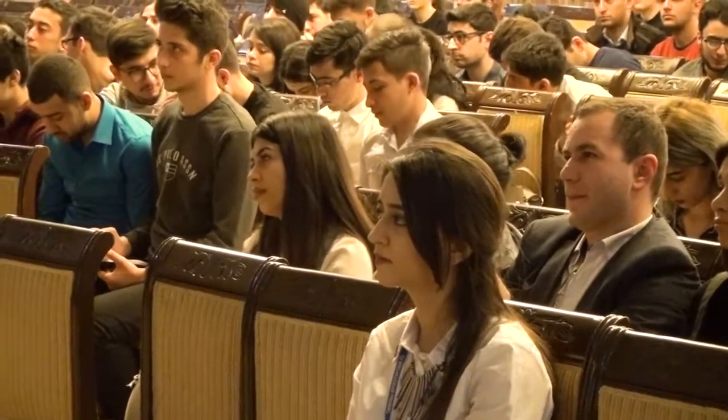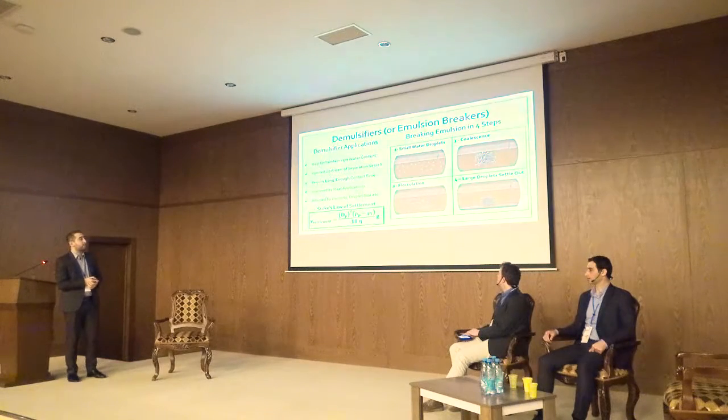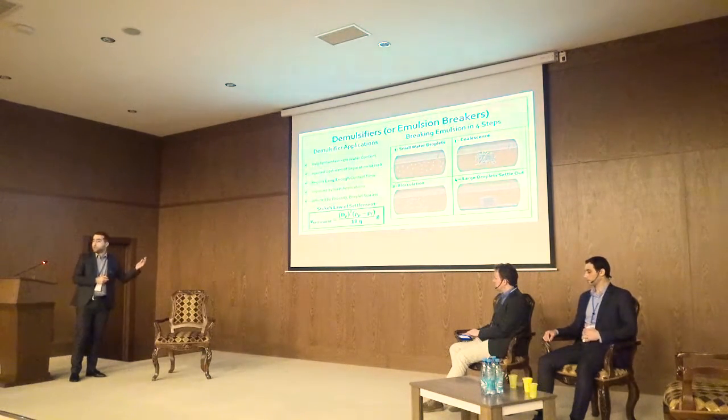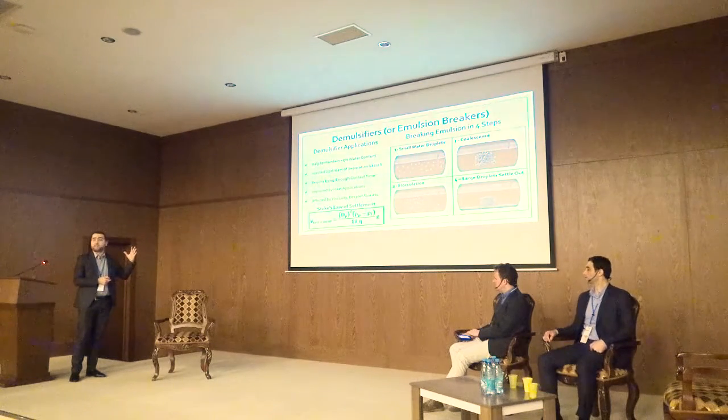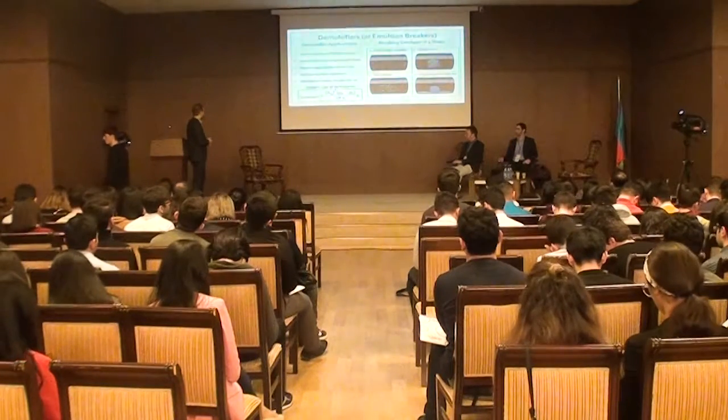So first of all, we have water droplets in this system. Imagine this is a separator. When we apply this demulsifier or emulsion breaker to the system, these molecules come and find these water droplets, and because they are surface active chemicals, they change the surface activity of these water molecules, and they become more attractive to each other, and in the third part, they coalesce. So they get closer to each other. When they are big enough to settle out, they just settle down here, which makes it easier to separate and get the water out.